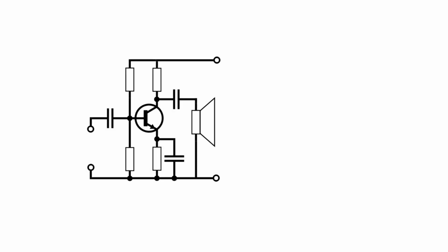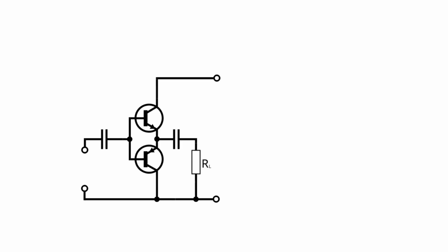The principle of Class A is that the transistor is always working in the active region and amplifies the whole signal. The working point of a transistor working in Class A is set to the middle of the active region, where most of the power loss occurs. This makes it the most inefficient for signals with low amplitude. Because of poor power efficiency, Class A power amplifiers are used only for low power, like for example preamplifiers in audio applications.